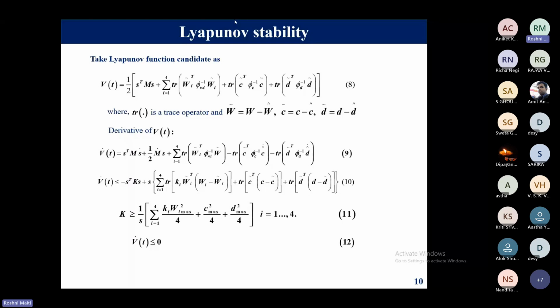Therefore, we have to put those things inside our Lyapunov vector. And ultimately, if we calculate these things again, we will have different values like this, and we will have our rate of change of energy, V dot, as a negative semi-definite function.